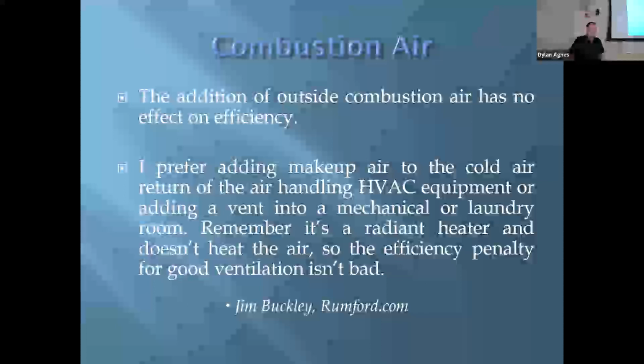Is that because the immediate outside air is too cold? Too cold. And he's saying if you use air from inside the house, it's already warmer. If you're pulling it through the HVAC system, it has a chance to temper. Yeah. It blends with the air in the house. It's being distributed through the duct system. So say you're pulling it off a gable end.